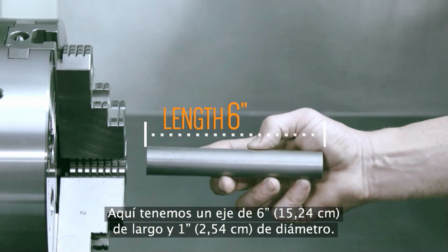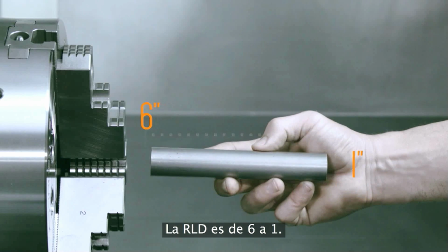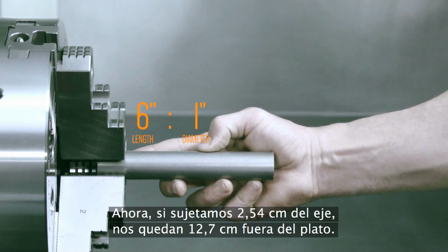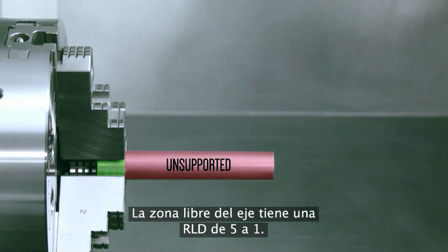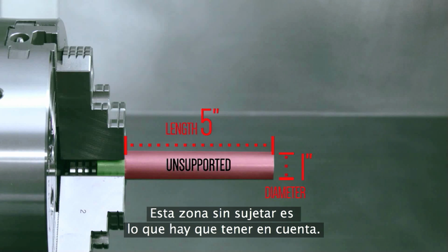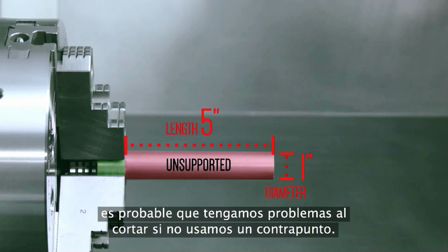Here we have a 6-inch long by 1-inch diameter shaft. Its length to diameter ratio is 6:1. Now we clamp this shaft 1 inch deep with 5 inches extending outside the chuck. The unsupported region of the shaft has an L to D of 5:1. This unsupported region is what we need to consider. With this much of the workpiece hanging out, there will likely be problems cutting unless tailstock support is added.